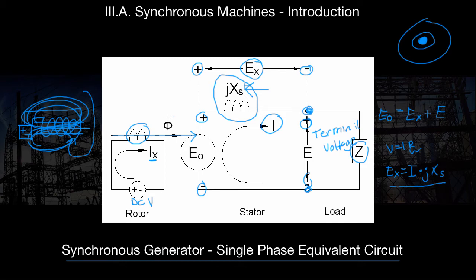Okay, what else can we say about our synchronous generator? Not pictured here, since this is an electrical diagram, is the mechanical component, our prime mover. You will oftentimes hear that, prime mover. Essentially, the prime mover is what converts the energy source, say steam, usually from burning a fuel, into mechanical rotational energy. Mechanical rotation.